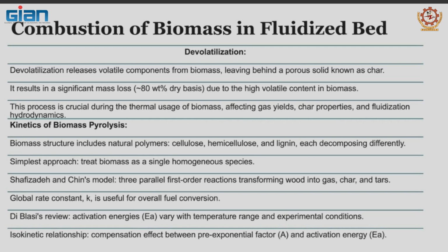And then they're transforming, if this is, for example, a wood particle, transforming it into gas, char. And of course, a consequence of this is tar, which I haven't mentioned so far, one of the biggest disadvantages of biomass, especially if you're gasifying it. Combustion is at high temperature, we don't need to worry about it, but if it's part of the pyrolysis problem, tars are formed, you make sure that it is burned. Anyway, you do this with three first order reactions.